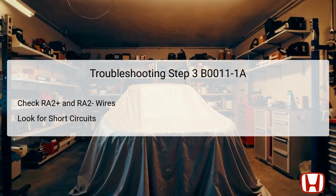In this phase of troubleshooting, focus on the RA2+ and RA2- wires to identify any potential short circuits or wiring problems. Begin with the proper preparation. Ensure that the SRS unit connector A is disconnected, as well as the front passenger's airbag inflator connector. Connect the SRS unit connector A, 43P terminals 8 and 9, to the SRS short canceller. This connection will allow for a detailed inspection of the wiring integrity in the IG mode.